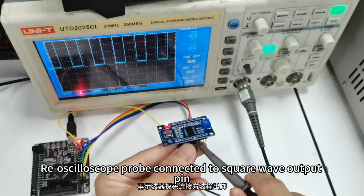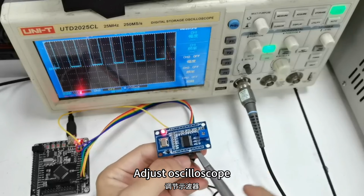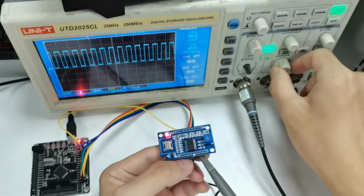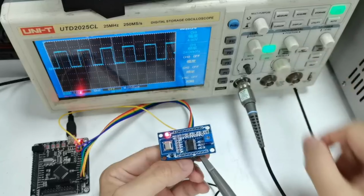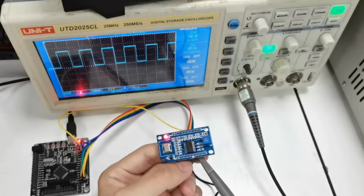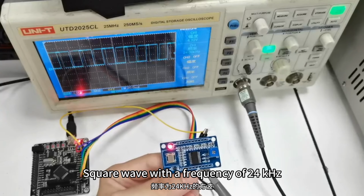Now the oscilloscope probe is connected to the square wave output pin. Adjust the oscilloscope. The observable amplitude is 5 volts. A square wave with a frequency of 24 kHz.